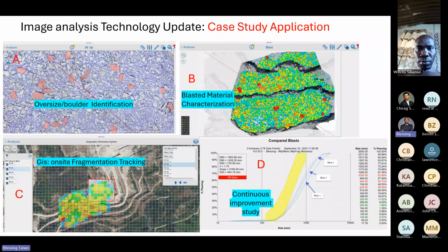All or any of these approaches you're using are capital intensive, and safety is also a concern. Some of us who are used to blasting boulders know it's difficult to blast a boulder because there is a high possibility of flyrock. Since you have a free face at every point in time, the boulder is in free space, so you can easily project particles if you are carrying out secondary blasting. Then what about the cost of buying explosive to do the secondary blasting?